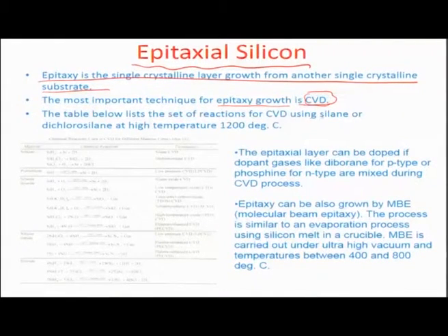For example, there can be the use of silane or dichlorosilane, as is illustrated here, silane being SiH4, dichlorosilane being SiH2Cl2, where through high temperature and through cracking of this gas molecule, you can generate silicon which is deposited as a solid phase, or maybe silicon chloride SiCl2, and it can further liberate hydrogen in the process. And then again, the hydrogen which is in excess in the particular chamber because of stoichiometric reasons again reacts to SiCl2 and formulates the silicon, and an acid residue.